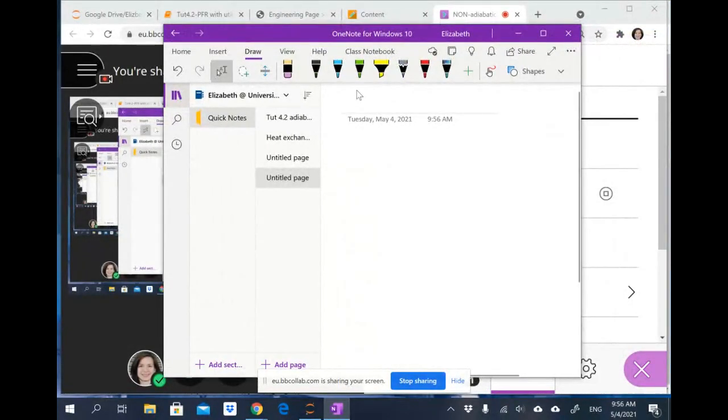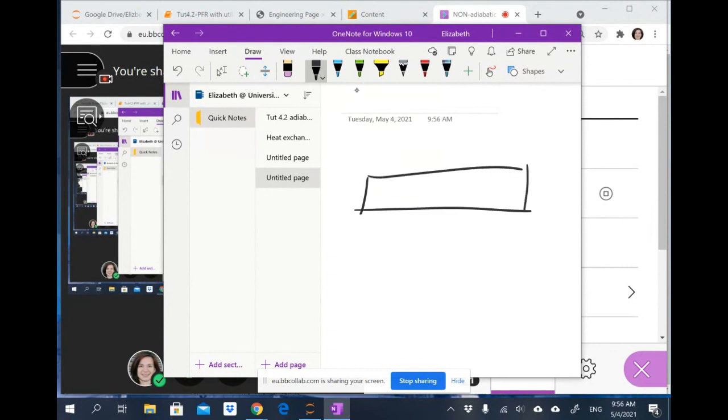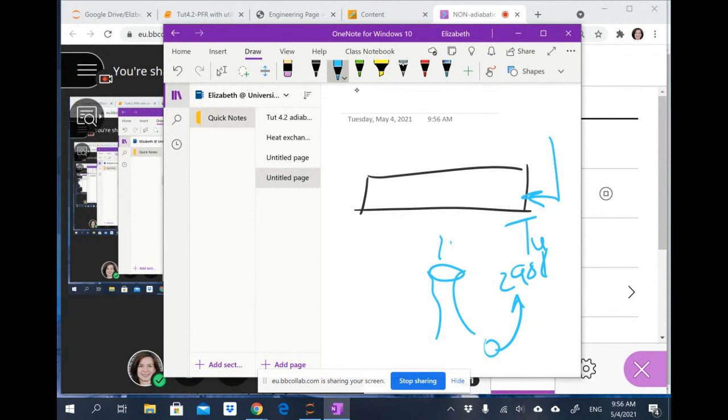Yes. Okay, so let's just draw this once again. So in other words, I know this is my reactor there. I feed my utility here at a utility temperature of 298 Kelvin. This is what I know about the utility because I've got a cooling tower, and it produces cooling water at 298. So this is where I pump my cooling water in, and that will be a known parameter. Okay, then it flows. Yes. So then we change our TU naught until the value returned by solve IVP is 298 Kelvin because we know that's our inlet.